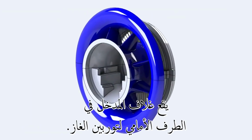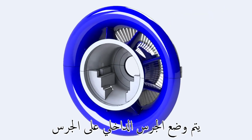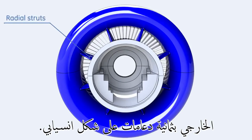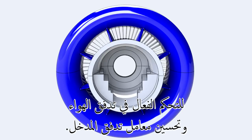The inlet casing is located at the forward end of the gas turbine. The blue painted section at the forward of the casing is called the bell mouth. The inner bell mouth is positioned to the outer bell mouth by 8 airfoil-shaped struts. The bell mouth function is to direct the air normally and uniformly to the inlet guide vanes for efficient airflow control and better inlet flow coefficient.